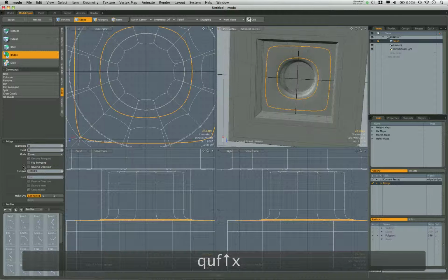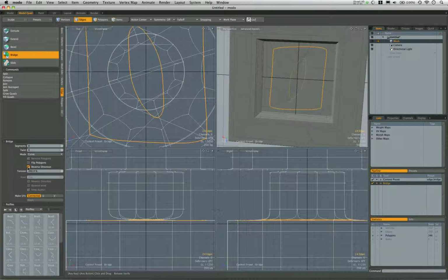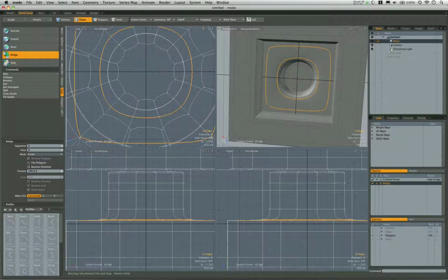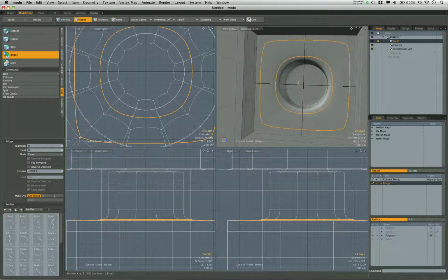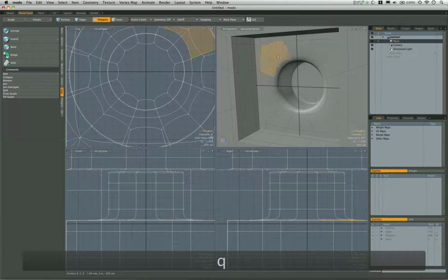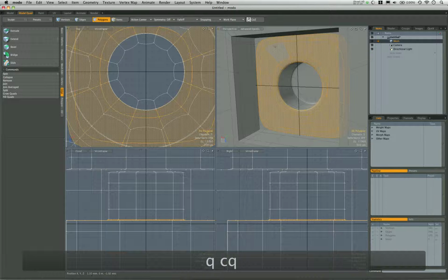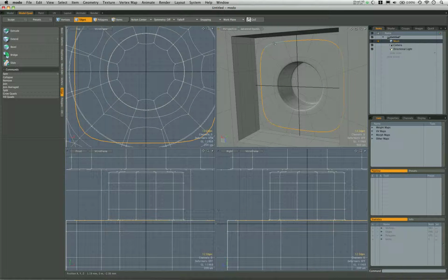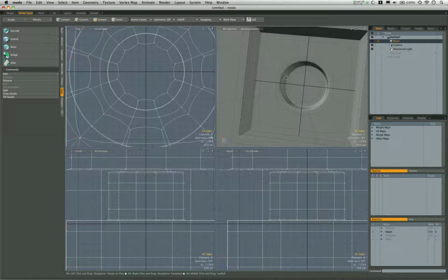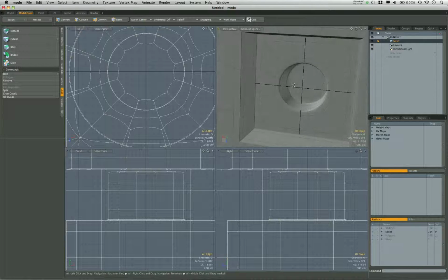Sometimes you'll get some things going funny. It might look like this, in which case you'll want to use the reverse direction checkbox here. We can see it's actually working, so we don't need to check that here. All right. So now all we're left needing at this point is an extra loop slice here. Again, we've got 2 set, so instead of going and switching all my settings, I'm just going to put it in there and then go back and delete that piece there.